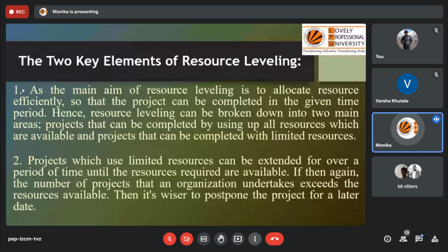Yes, two situations may arise during construction. Sometimes the resources are limited, and we need to complete our work within those limited resources. Or in another case, resources are available in plenty, but we just need to complete the project, where we do not focus on resource availability. The focus is to complete the project, even by allocating more resources or over allocation. Okay, so these situations can be there, but resource leveling may help to achieve both of them.